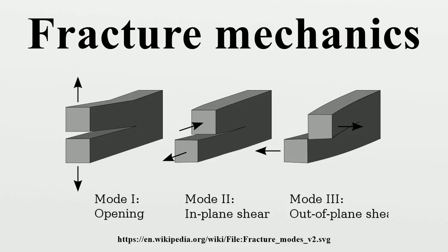Naval Research Laboratory during World War II realized that plasticity must play a significant role in the fracture of ductile materials. In ductile materials, a plastic zone develops at the tip of the crack. As the applied load increases, the plastic zone increases in size until the crack grows and the material behind the crack tip unloads. The plastic loading and unloading cycle near the crack tip leads to the dissipation of energy as heat. Hence, a dissipative term has to be added to the energy balance relation devised by Griffith for brittle materials.